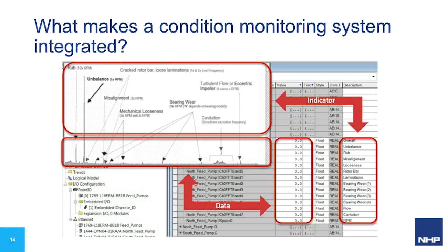The nice thing about it being inside your control system or your PLC, we can apply if-then logic. I've spoken to a lot of customers that say, look, when a valve is open, we get different process conditions, or when there's a machine crushing next door to the process that we're doing here, we're not going to get an accurate measurement. We can apply if-then logic, and this is easily modeled within a controller.